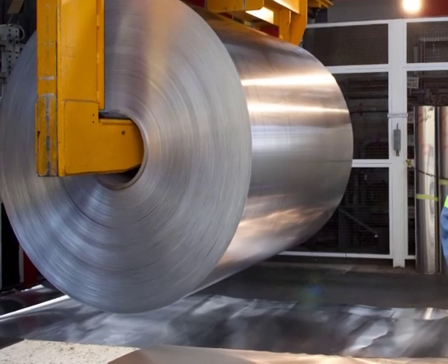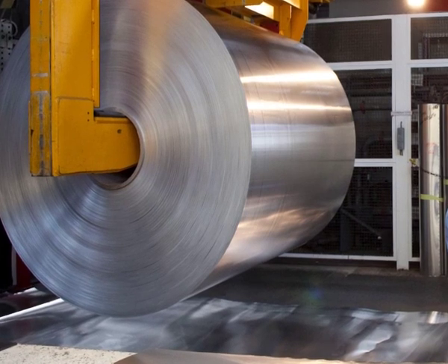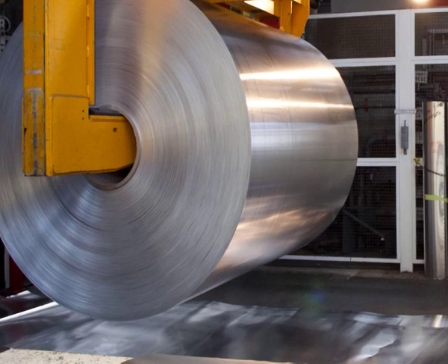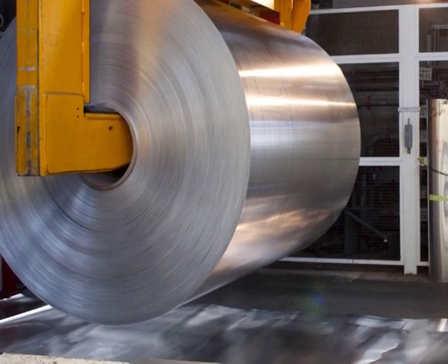In the past few years, the process of drawing and wall ironing has enabled continuous side wall containers to be produced from both aluminum and tin plate sheet. Unlike two-piece extruded body containers, these containers have no base chimney but instead have a seamed on cone.